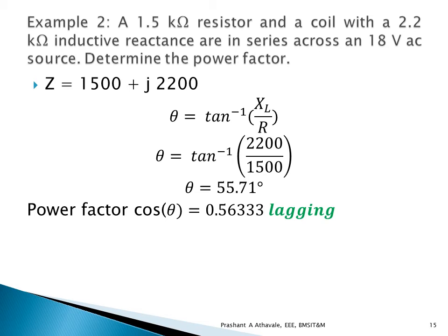So to determine power factor, all that I require is the resistance and the magnitude of the impedance, or inductive reactance and the resistance. So using either of these, you can definitely find it. So let's read the description of the numerical example.